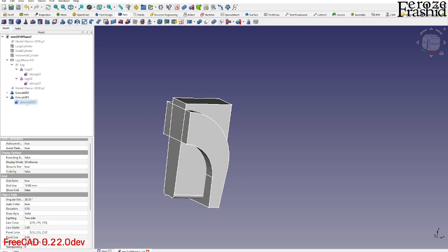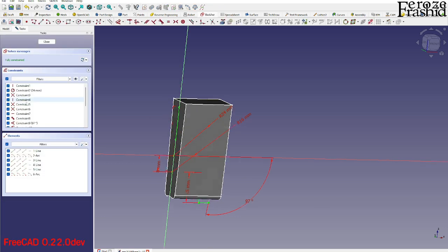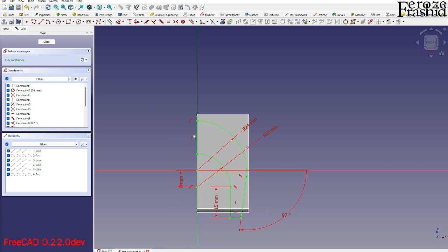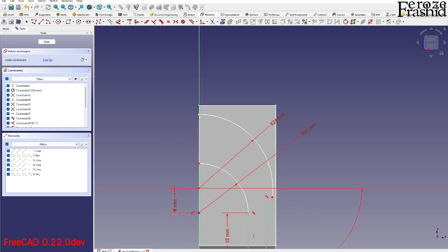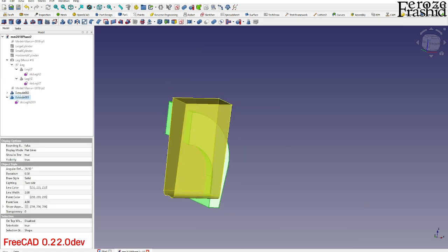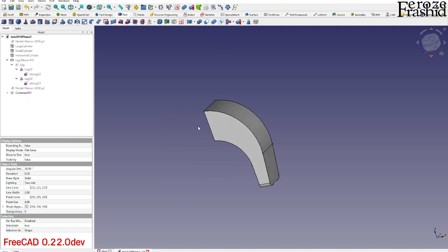So I'm gonna go ahead and take one of the sketches and maybe push it inside, say 1 millimeter. So that will give some overlap. Let's see if it worked. Yeah, it worked. So as I said, it happened to me one more time before, and that's the one way I think of it. Just push one of the planes from each other. That helps.